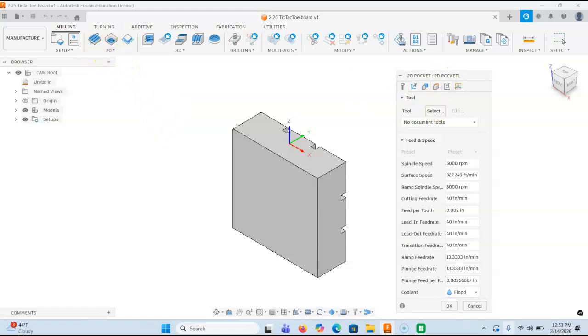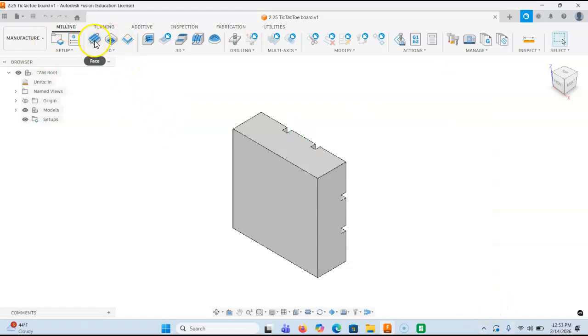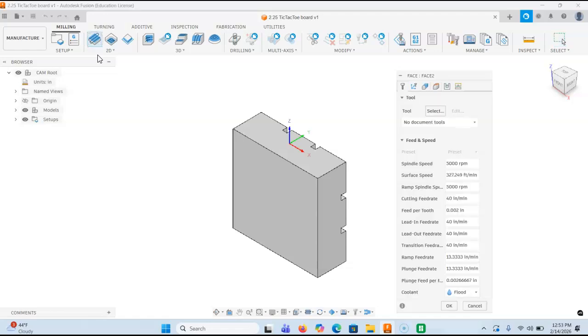So let's go ahead and head back over to the face milling again. As we talk more about face milling, one of the successful CAM strategies is to start with some of the largest cutting tools that you have, so that you can minimize the number of passes that might need to be taken. So we've got to face that off. There's a sequence here that needs to be followed. And of course, if we follow correct tool feeds and speeds and sequence, that's going to lead to longer tool life, less machine time, and final part quality as well.